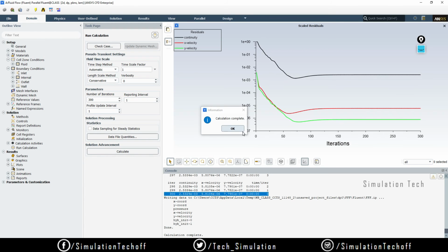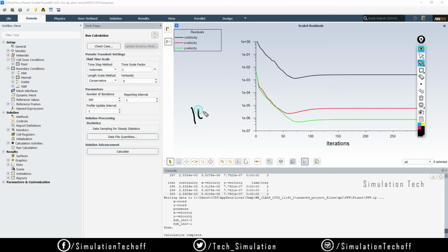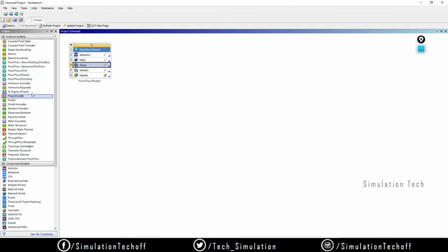Okay, so there might be a lot of reasons why the problem is not converged. So how can I make sure, sir, whether my problem is converged or not? All the values should be below, the difference between the two numbers is 10 to the power of minus 6. It's a very minimum thing, like 0.00. That difference will be allowed. So when the two previous values are equal, the problem is automatically converged. So what I simply do is change the mesh configuration. If you get a poor quality of mesh, you may end up with non-convergence.